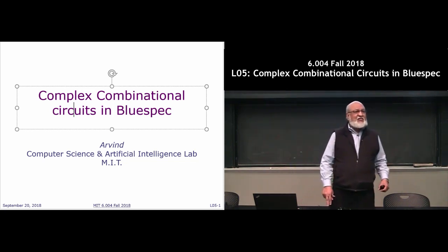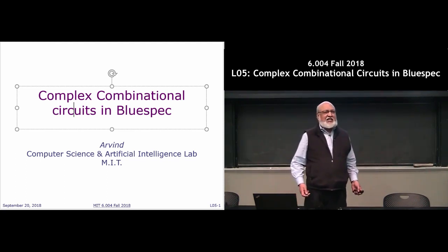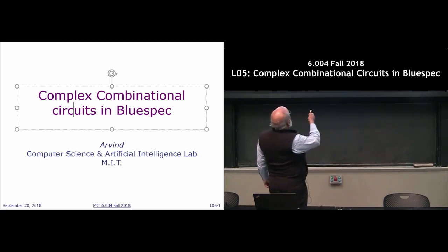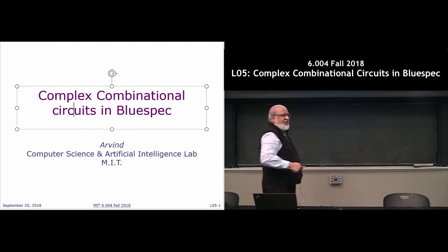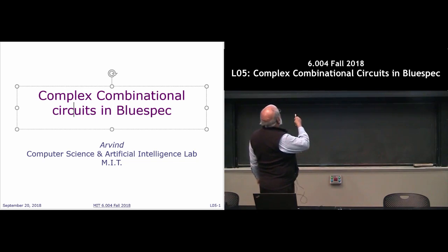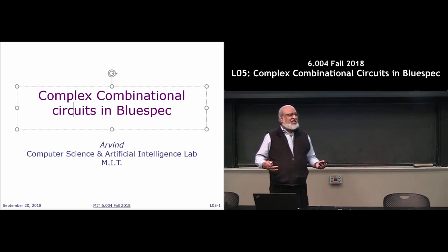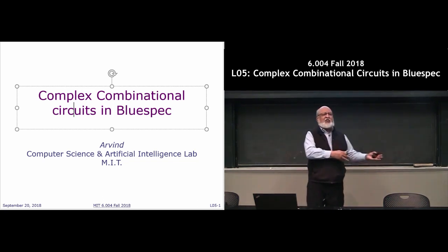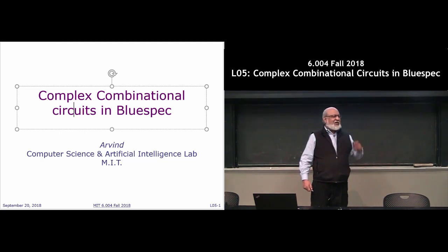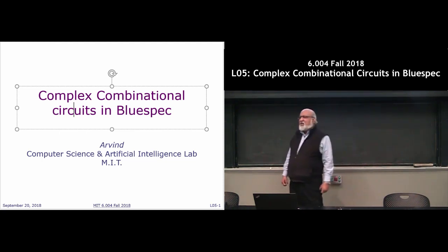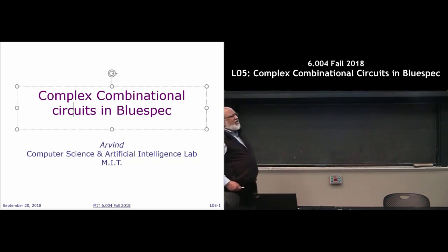Does it look at what you're trying to output and return W from that? Exactly. It looks at the left-hand side and right-hand side. And it says, aha, you are telling me x is 3 bits, so I'm going to assume x is 3 bits. So it's instantiating based on the output you're demanding. You're saying, I want a circuit which returns 3 bits, and I'm going to feed it x and y, which are 3 bits long. The compiler knows all that. It says, aha, that's what you must have meant. And if it can't decide all this, it'll say, sorry, I can't figure out what you're trying to say.